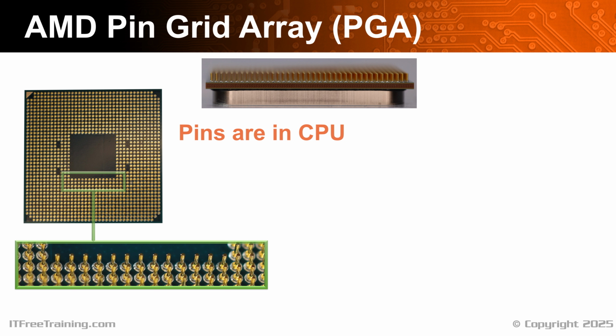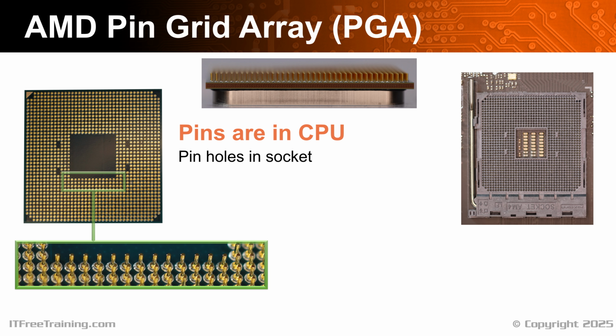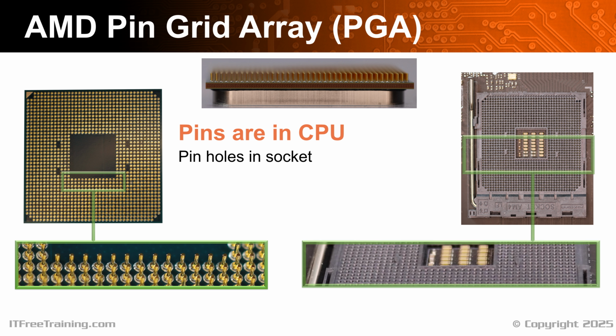The motherboard has a socket for the CPU which has socket holes that the CPU goes into. For each of the pins on the CPU, there'll be a socket hole for that pin. The socket holes are essentially made of plastic to prevent the pins being damaged. However, if dirt or dust get into them, this can affect the connection to the CPU. As with the Intel socket, it is a zero insertion force socket.